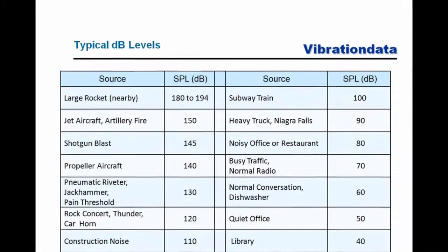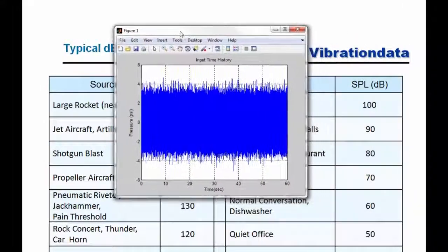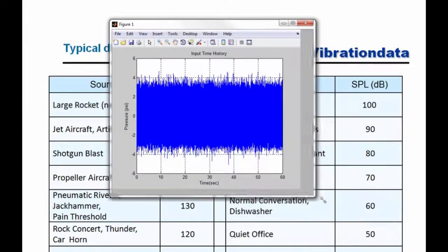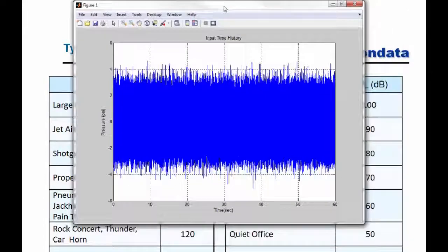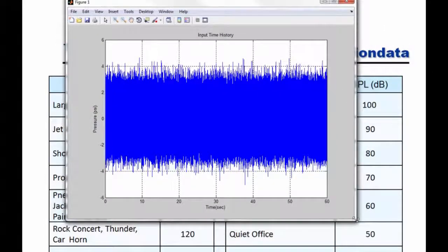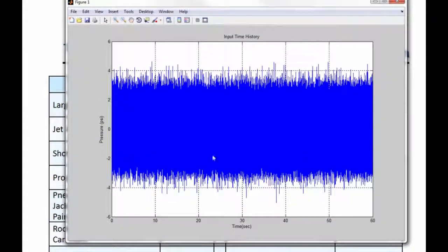Now I'm going to be honest with you. What we did today was just a little bit contrived. And in a future webinar, we're going to study high-intensity acoustics. Because what really happens here is that the higher up we get in acoustic level, the more skewed our data becomes. And the reason for that is our negative pressure can never drop below minus 14.7 psi.